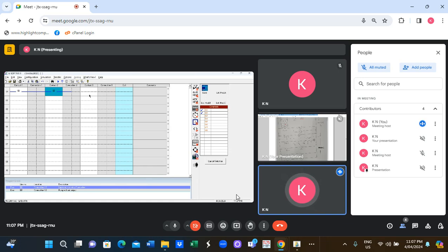After I insert I1 and I2, I will insert the relay coil and the light. The light is an output. I will put the relay coil and the light, and the light goes to the output, which is Q1. So in this case the light is the output, and I will select Q1 as the output light.